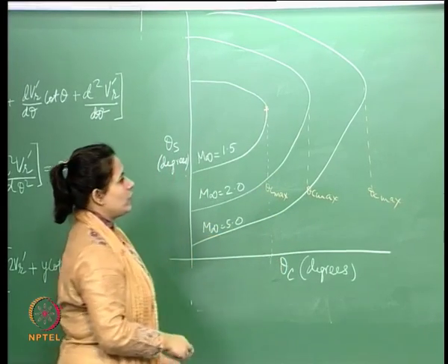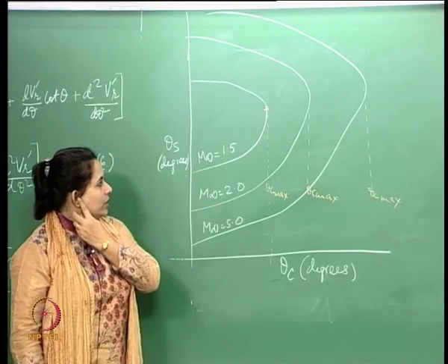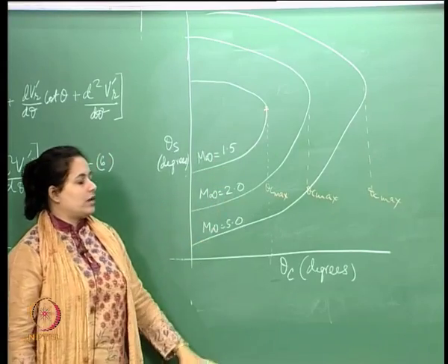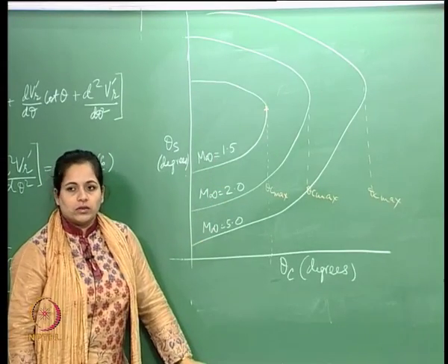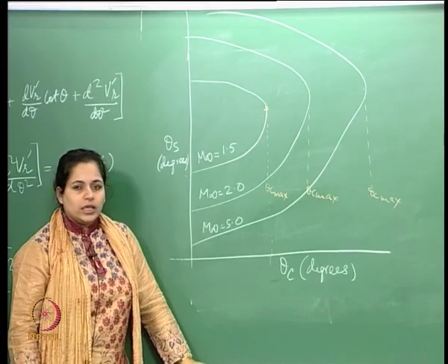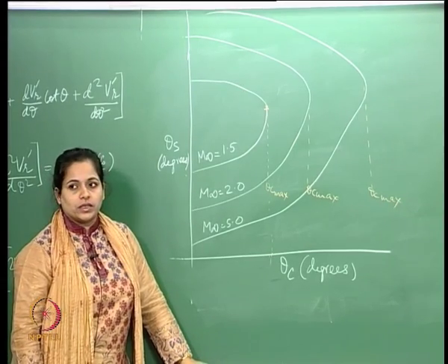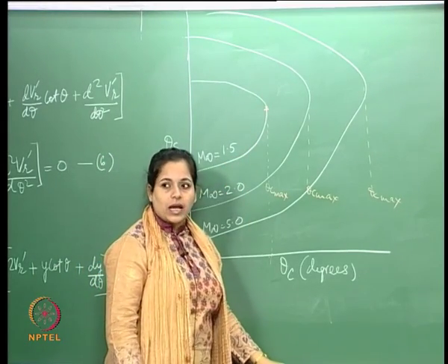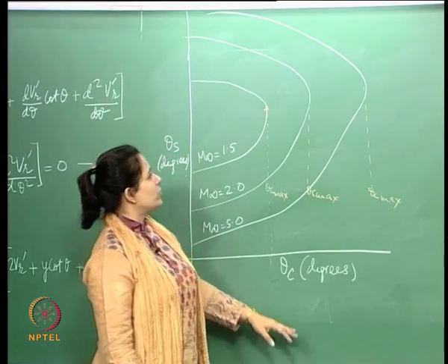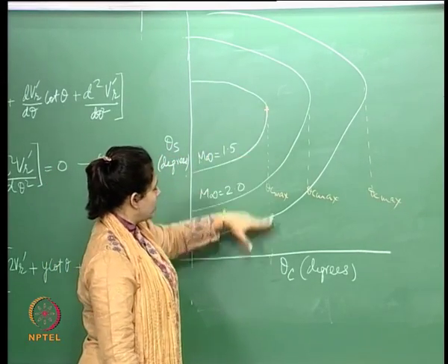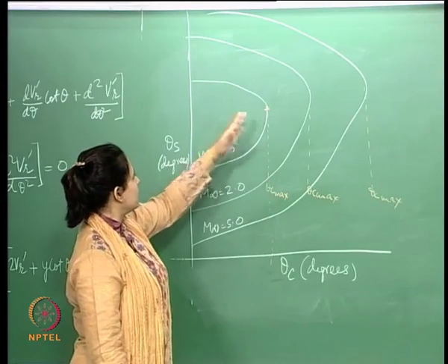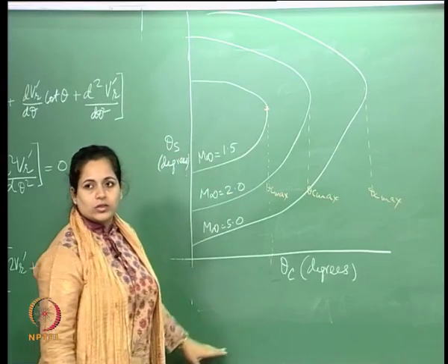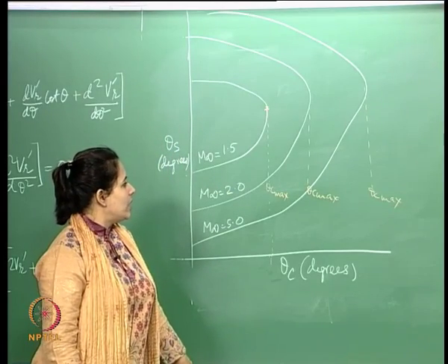So, say if you have a Mach 1.5 flow and you have a theta c which is larger than this corresponding theta max, then you will not have any solution. The Taylor-Maccoll equation is not going to give you a solution past it. Okay. So, essentially after this the shock is detached. So, the Taylor-Maccoll equation is going to give you solutions only when your theta is less than the theta max. So, this is also like we did for the wedge.